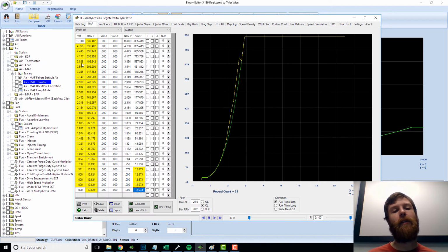So what that means is in this particular log, I did mash the throttle a little bit, and now it's freaking out up here and thinking that I need to add like 20% more fuel, and that's completely false. It's thinking that because that oxygen sensor can't even read that rich, and it doesn't know what to do, and it's totally telling me to do some very stupid things. And this is why you never want to just paste in this whole table. But since you're only focused on idle, you're probably going to be down in these bottom cells right here.